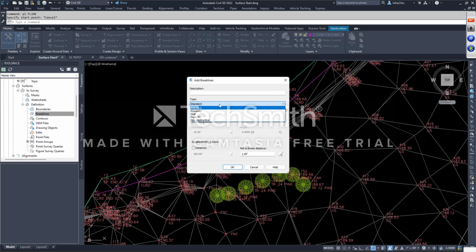There are 4 different types of break lines allowed, actually 5. Standard is what I would normally use for a polyline without any elevation, okay? And that will just force the TIN to change direction when it runs into that polyline. Proximity is similar to standard. Actually, these two kind of go hand in hand. Standard can use the 3-dimensional elevation. Proximity is the one that you use when all you have is 0, so it knows that there's a proximity and to change direction. Standard is the same setup as proximity, but will also use the elevation of the polyline if it has elevation. A wall is literally a wall, okay?